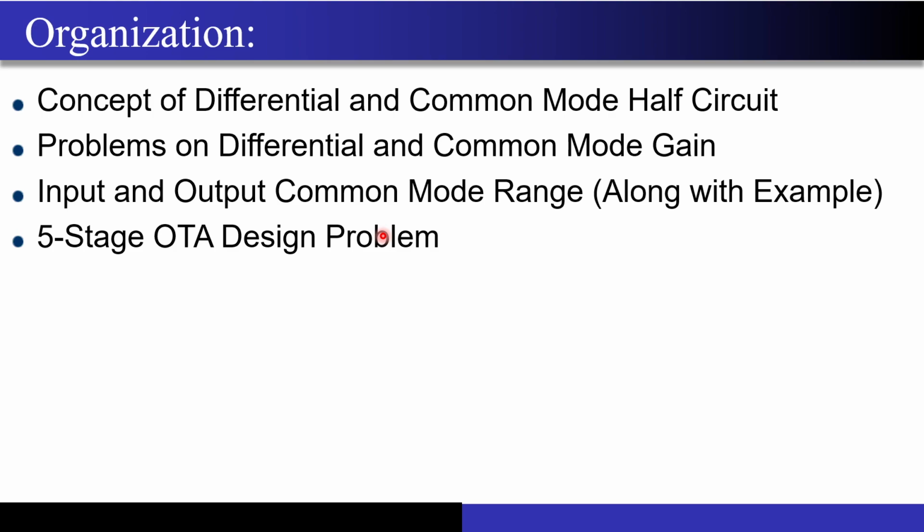So this will be the organization of this session. First we will have a quick look at the concept of differential and common mode half circuits, which will help us get the output response of any differential symmetric circuit with respect to the common excitation or the differential excitation. Then based on that we will solve at least 3 or 4 different problems, and then we will move on to the concept of input and output common mode range.